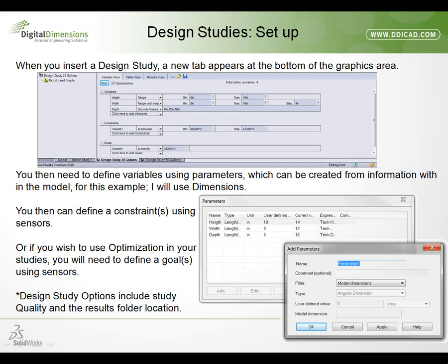Well, if you have this set to low quality, then SOLIDWORKS will go through and it'll pick iterations to run, and then it'll interpolate or extract the rest based on a trend. After it presents you with the data, you'll then be able to go through, and the items that it did not actually calculate, you can go through and have it run those iterations to find out if the trend that it predicted was accurate or not.